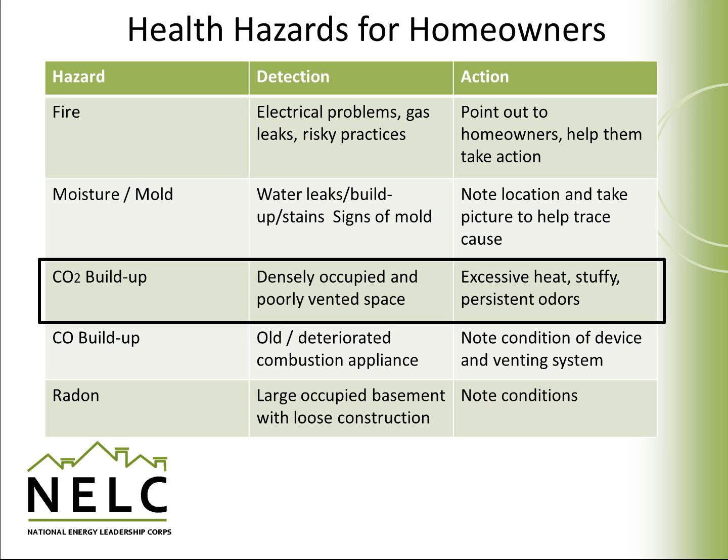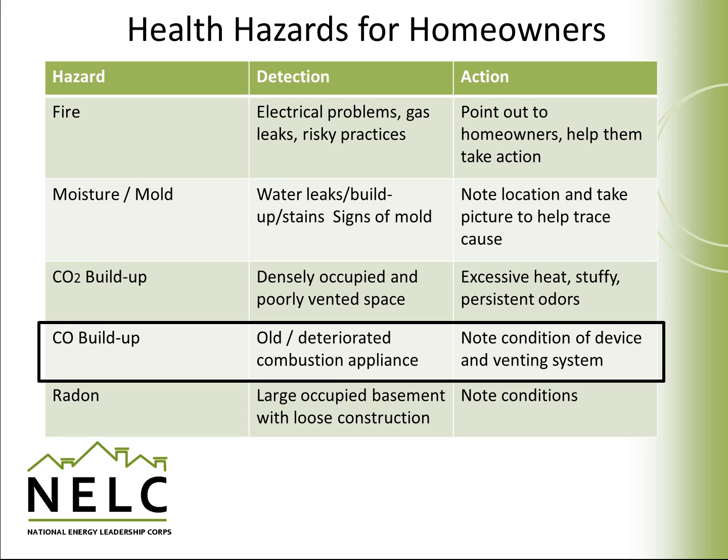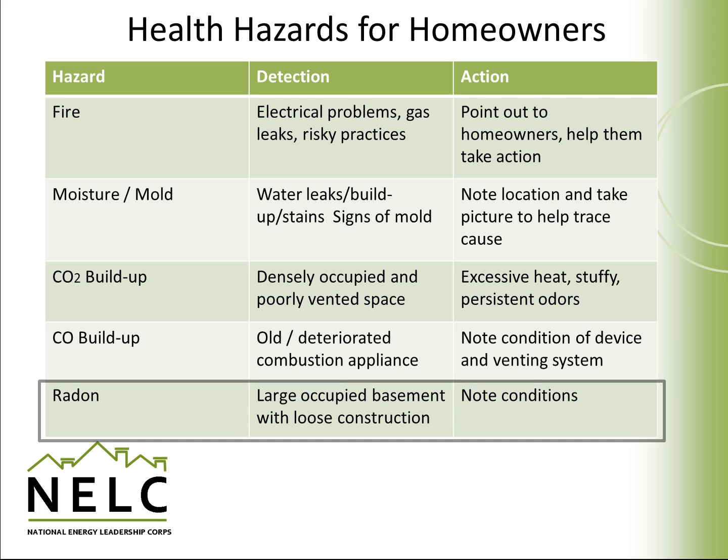Carbon dioxide buildup can happen in densely occupied rooms and overcrowded spaces that don't have good ventilation. This can have some harmful effects over a long period of time, and we'll be taking some time to examine what to do about it. Similarly, carbon monoxide is another hazard we'll be looking out for. This is typically a product of incomplete combustion, so anytime you're burning a fossil fuel, you have the potential for carbon monoxide to be given off. There are detection devices and ventilation systems that are intended to help deal with this. It'll be important to spot these and look if detectors are present, and if not, point that out to homeowners.